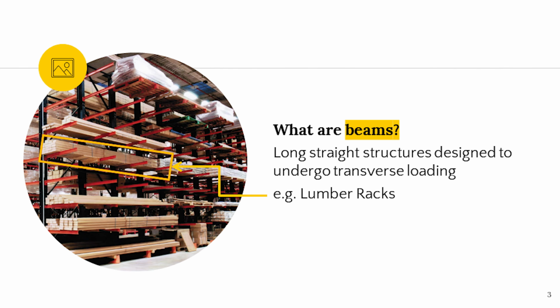Beams are long straight structures designed to undergo transverse loading. Designing beams requires a good understanding of the variation in the internal shear force and bending moments at each point in the beam. These internal forces are key to identifying potential points of failure in the beam as they directly influence the stress and strain.